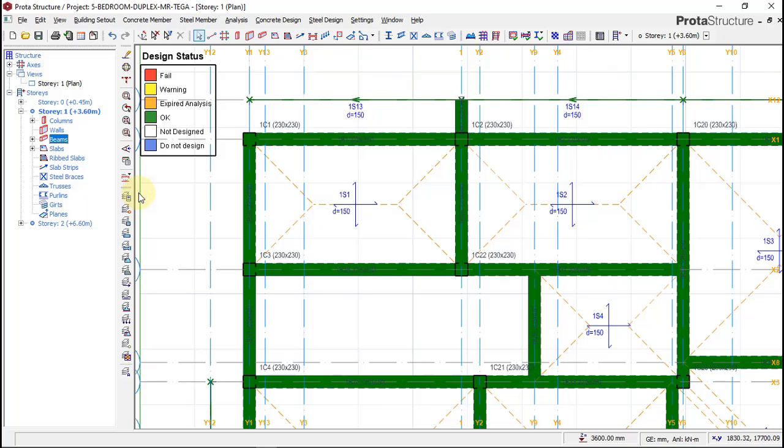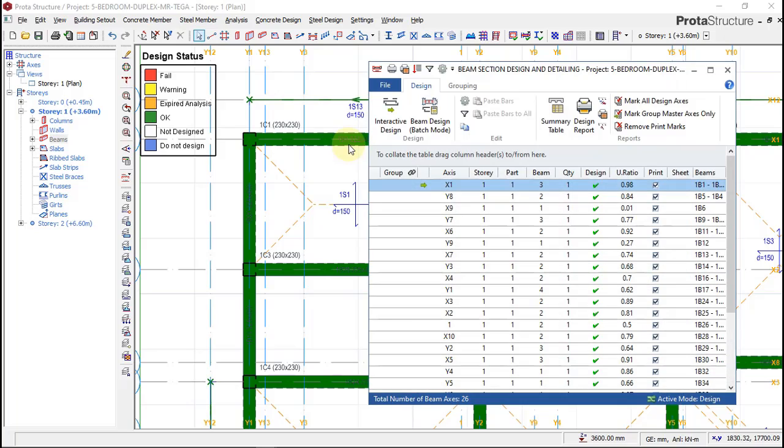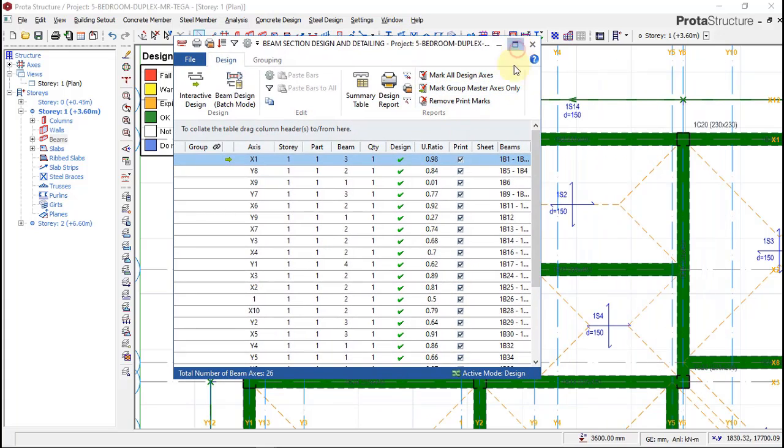So I'll wait for it to come up. It's always good to check the beams to know the kind of design the program performed, to see if the program used the specification you specified for the reinforcement. We used only Y16 for the reinforcement of all beams. Now this program can go ahead and give you a reinforcement size of 25. Why you don't need that? That's why you need to check the beams one after the other. So with this now, I will start checking my beams.